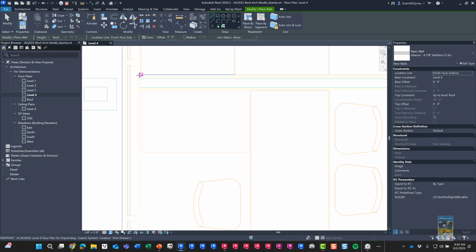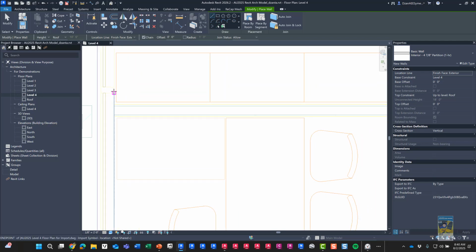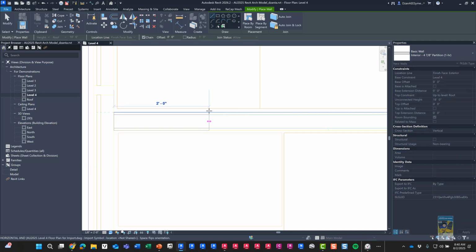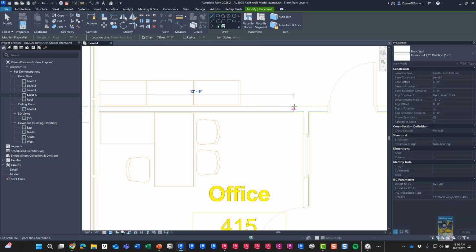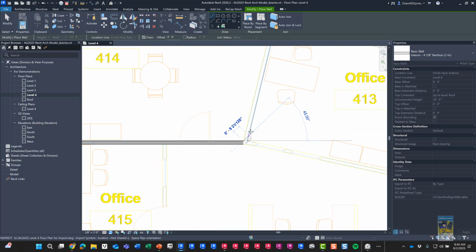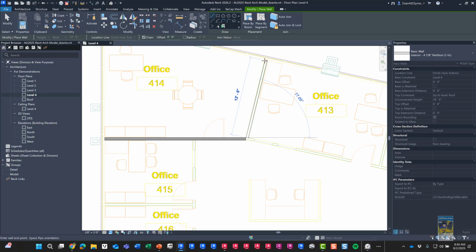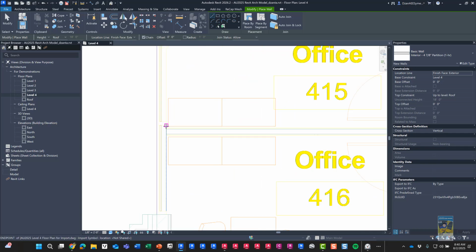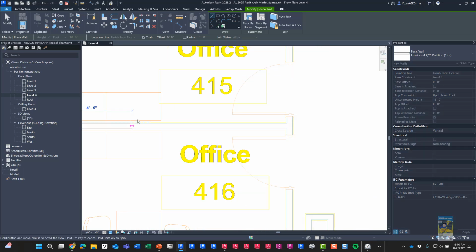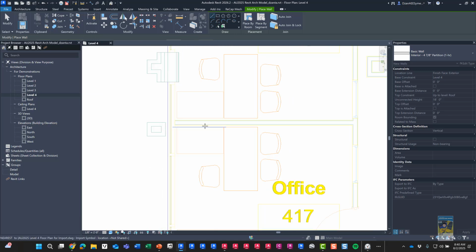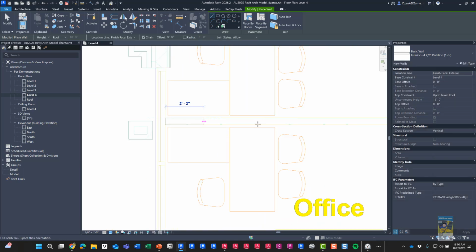As you can see with the CAD file, it sees the data and you can actually click and pull and it will snap into the geometry, okay? Now, for the purposes of this lab, I'm going to give people 15 minutes, maybe 20 minutes, depends on how fast people can work. So go ahead and at this point, bring in your CAD file, make sure you've got to this level, and then start modeling walls, as you can see here.